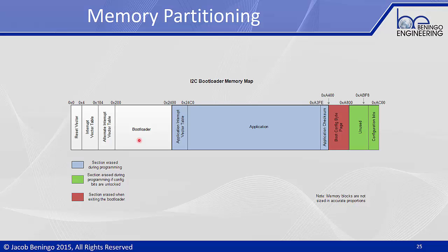Now, depending on the type of system you're developing, it could be that you're now throwing away a $20 board, or it could be that you're throwing away thousands of dollars of hardware simply because you made a mistake developing your bootloader. So keep in mind, you want to try to look in your data sheet to put this in a secure location where you can protect the bootloader.